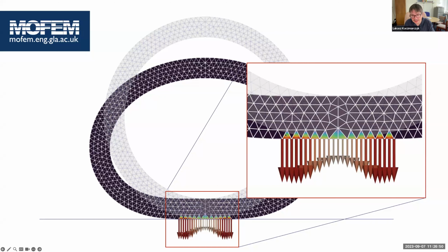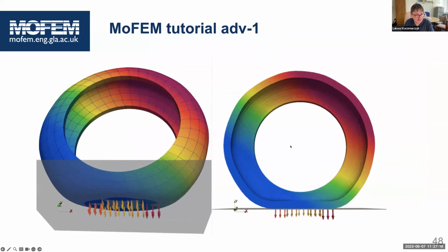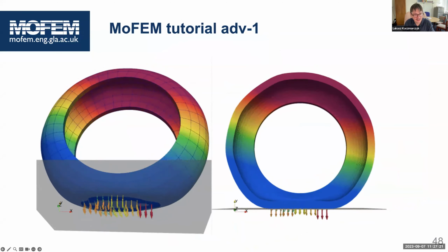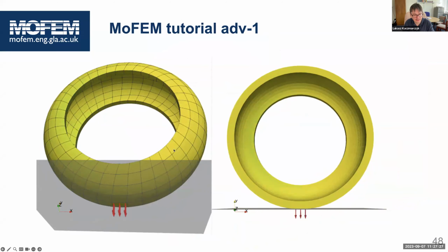But when I calculate the sum of the integrals in our formulation, because it's HD space, I can calculate in the volume. Only integrals which are associated with the Kuhn-Tucker constraints, with complementary functions, are calculated on the boundary. That gives us stability and removes the oscillation. Then you can solve more complex problems immediately, and everything works, you can see, with hex meshes in a stable manner, and you can have a large curvature of those elements.